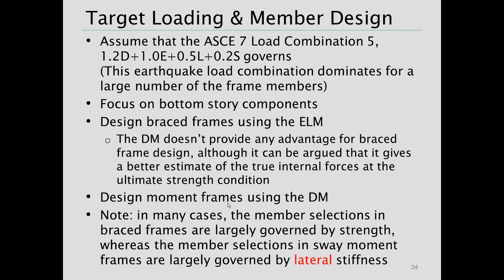When we go to the moment frames, we'll use the direct analysis method for the moment frames, and so I'll highlight where the direct analysis method calculations come in for that. Now, an important thing to keep in mind, which I know many of you as practicing engineers probably know very well, in many cases the member selections for the brace frames in a building like this are going to be largely governed by strength, whereas at least a decent fraction of the members that we're going to size in our sway moment frames often will be governed by lateral stiffness.